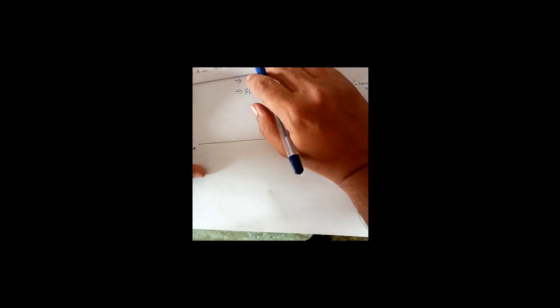And point A is also here. Point A is 15 mm in front of VP means A is 15 mm below XY line. This I have already explained in the previous video, that is to locate a point. If the point is above HP means front view is above XY line, that is front view is denoted by dash. That means point A is 10 mm above HP means we will be naming it as A dash, and it is above HP means above XY line, 10 mm above XY line.